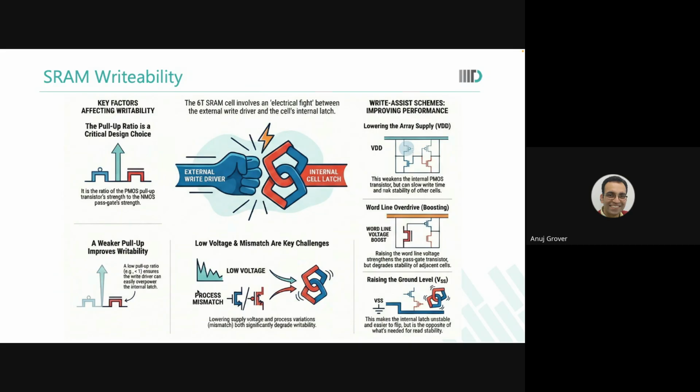Because if you trigger that charge pump somewhere here, what was the role of the charge pump? Taking it down by minus 200 millivolts. Now, if the bitline is at, let us say, 100 millivolts, then minus 200 from 100 is only minus 100. Your design may fail.